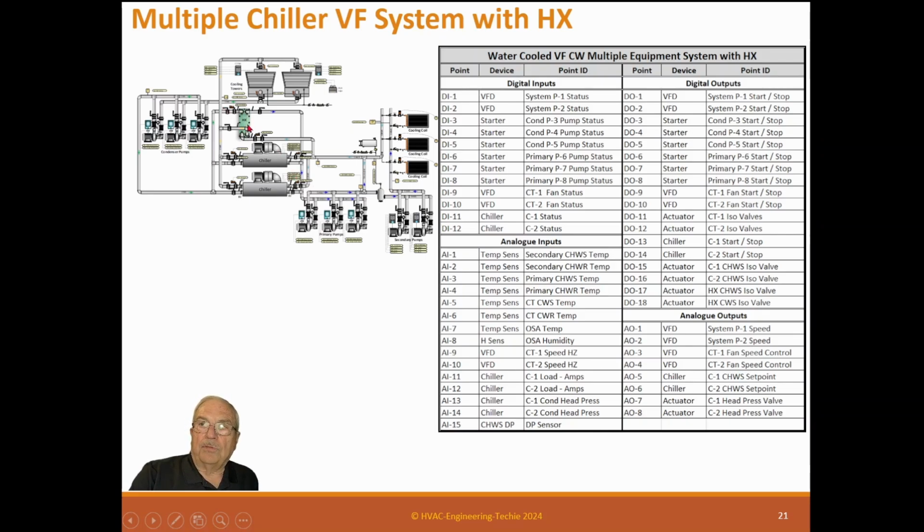Now, the problem with these is when you switch back to chiller from heat exchanger. To make this work, we drive this temperature down to the absolute lowest temperature. This may be 45 degrees up here in the cooling tower. Well, this chiller cannot handle 45 degrees under any circumstances. So there's 2 things that I would recommend doing.